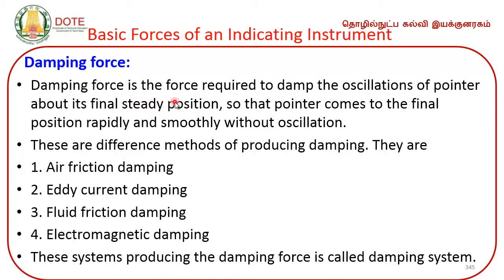The damping force is the force required to damp the oscillation of the pointer about its final steady position. So at the final steady position, to stand without oscillating, we need a damping force so that the pointer comes to the final position rapidly and smoothly without oscillation.